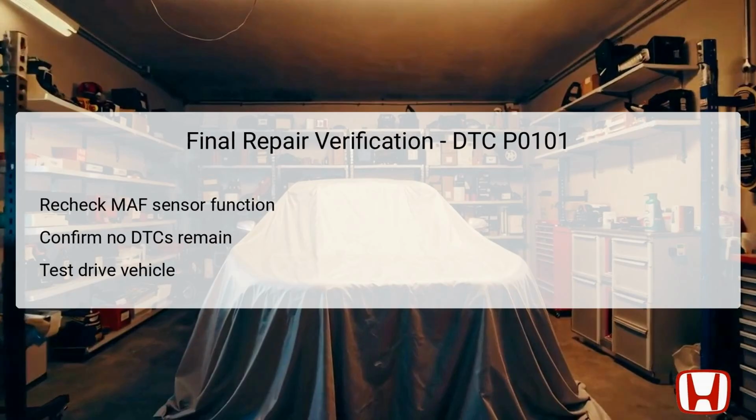Once troubleshooting is complete, the final repair verification step is essential to ensure that the issue signaled by DTC P0101 is fully resolved. This involves a recheck of the mass airflow sensor function, monitoring its outputs through the Honda Diagnostics System, HDS, again, to see if normal readings have returned.